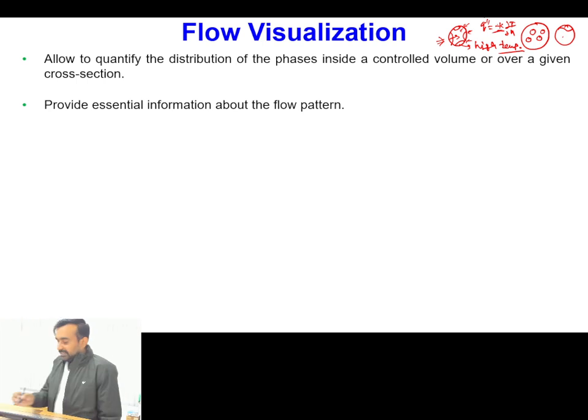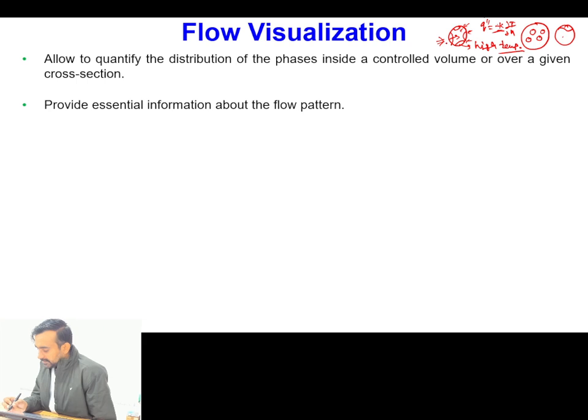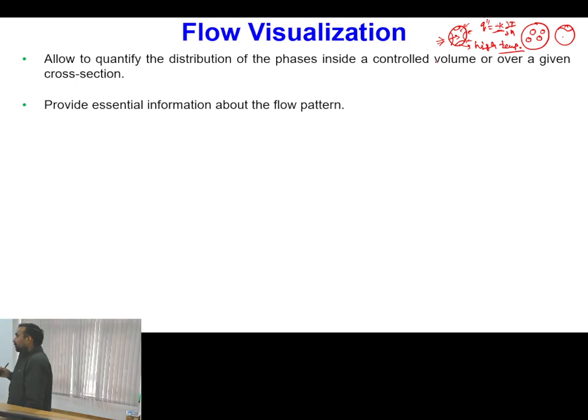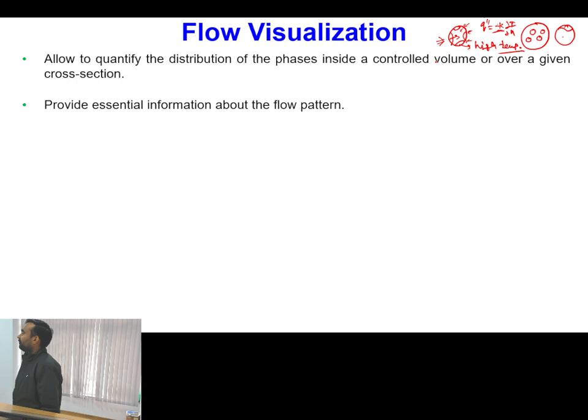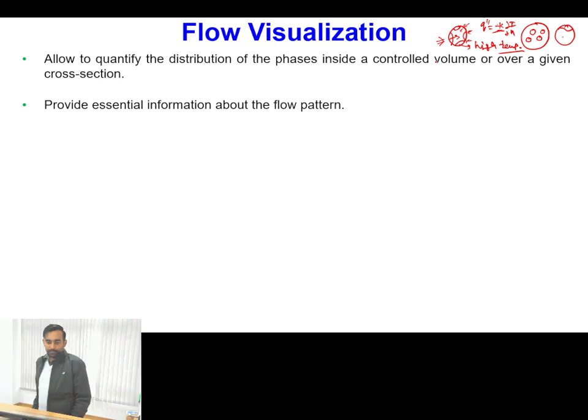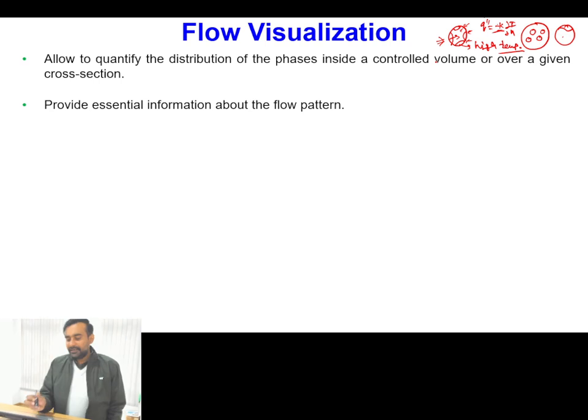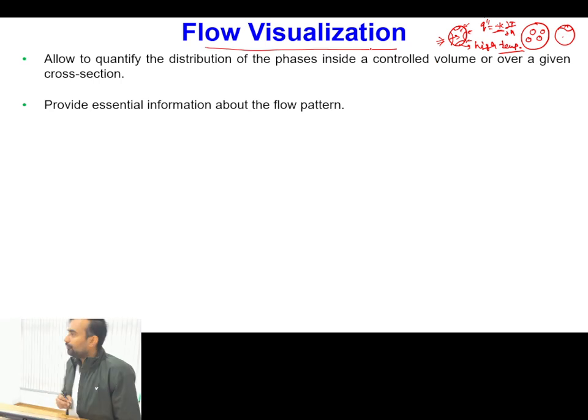Okay, so it means that it is not only the amount of gas at a particular cross section which is of importance for designing various multi-phase flow systems, but the understanding of the presence and distribution of different phases within the cross section is also important. Okay, so because of this we have to extend our analysis to flow visualization.